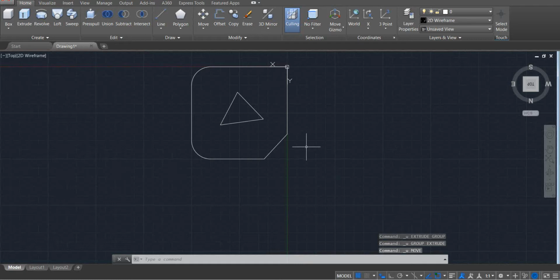The key idea is that we should have a two-dimensional sketch. This two-dimensional sketch should be a closed loop and joined. If it is not joined, if you forgot the join step, you're gonna end up with surfaces. Surfaces mean that you didn't join these loops together.